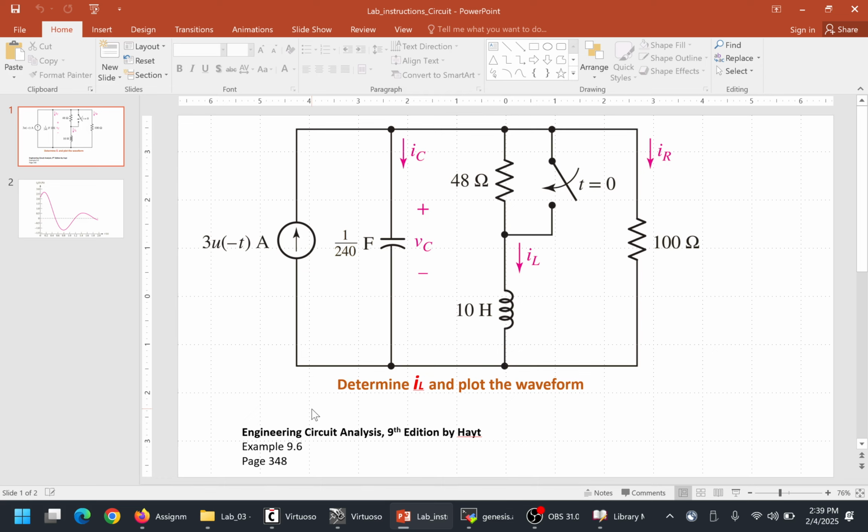A switch is a switch. You turn it on. During the simulation, we have no capability to click the mouse and turn it on, so we want to automate everything. For the automation, I have to come up with an innovative idea. The idea I've chosen is a piecewise linear voltage source, and I'm going to program it now. You will see. We'll program it to simulate that condition: it stays off until 1 second and turns on at the very next moment.